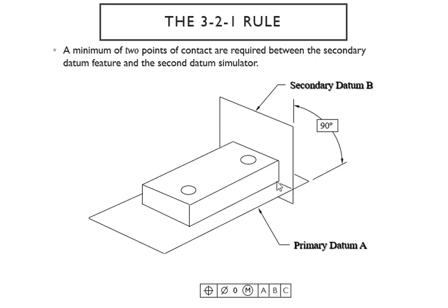So as long as they're all on the surface, you don't necessarily choose the 2 points in the middle part. If you choose the 2 points in the middle part, that would be just a contact with the bottom surface. You can also choose the point on the edge of it. So on the edge, you're connected to the second datum or the tertiary datum. Okay, so this is how you take it.